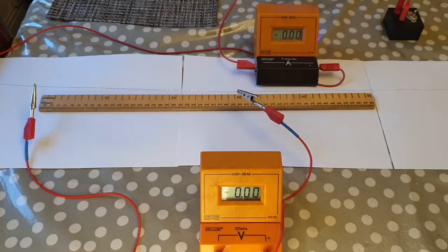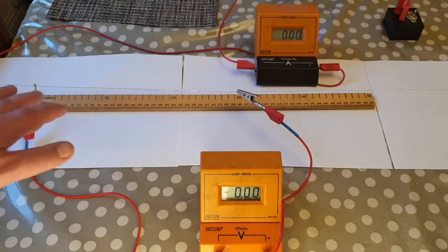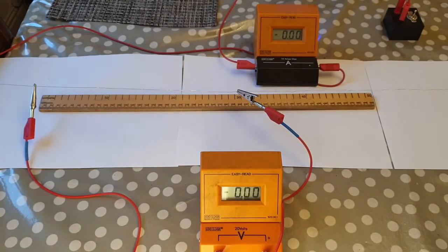To be honest, copper's not the best material to do this experiment with because it has a very low resistance. However, it was the only bit of wire I could find in the house, so I'm having to deal with it. So the actual material of the wire itself will determine what the resistance is, as well as the length and the cross-section area. Copper has a very low resistance for a given length or a given cross-section area. Other metals will have a higher resistance, and then you move into semiconductors, which have a much higher resistance, and then insulators, which have a vastly higher resistance for a given length and a given cross-section area.